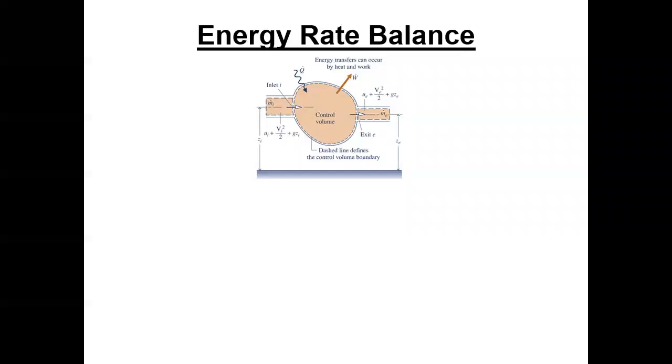You could have electric resistance, electricity flowing across there as a work term. You can have a paddle wheel. You can have any of our work modes. You could have the boundary of that control volume, like a balloon blowing up, and that boundary is PDV work. Any of those work terms. So that cap W dot is the net of all of them considered together, okay?